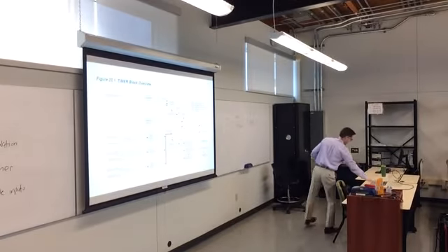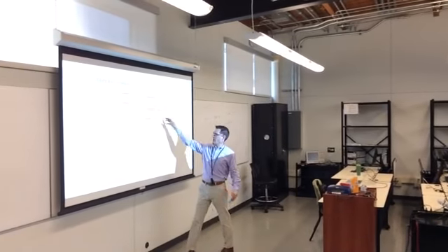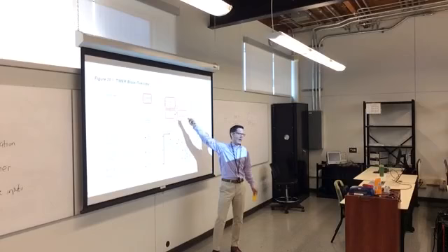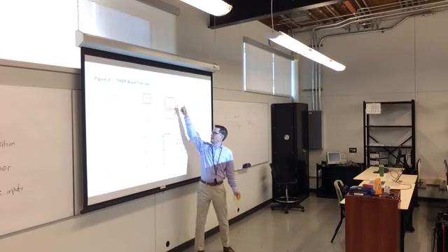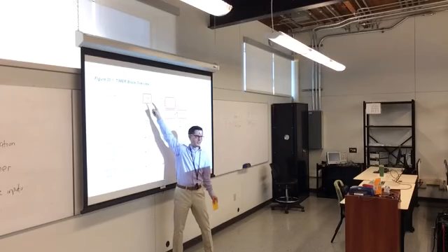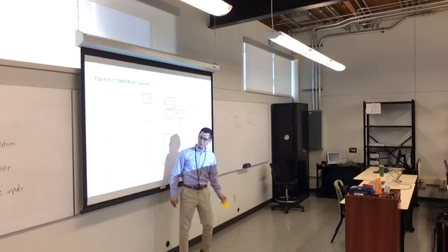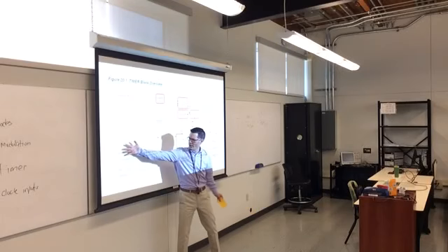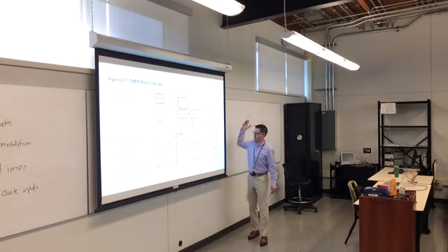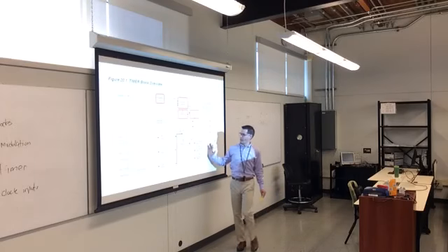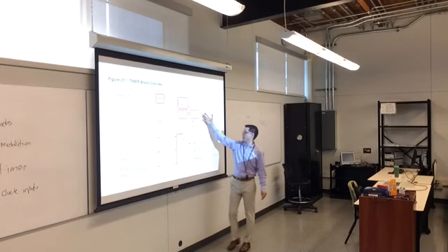So the 4 things you really care about are the top value. Count holds the current value. So this is your register that holds the current value. This is the control register, and this is the prescaler. All this other stuff is in here. It's useful. Here are the other inputs that are coming from the PRS system driving things. These are going out to other timers. A lot of this is the PWM and the capture and compare system. This is your basic timer functionality.